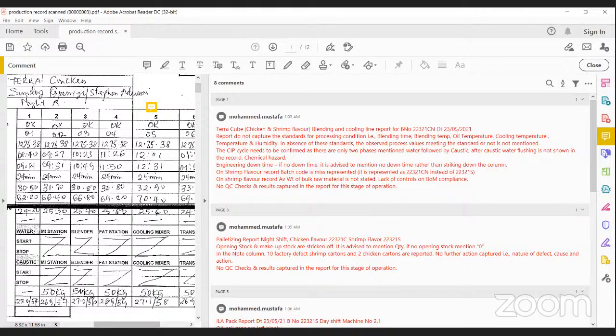Fumilola, have you done the cleaning validation for the CIP? Yes, we do swab after they clean. So the recipe, the concentration of caustic, the recipe they are following, do we have the data to validate the CIP recipe? The only data we have is the swab after they're done, and then to confirm that the caustic concentration is what it should be and that it's cleaning at that concentration. Okay, good. Thank you very much.